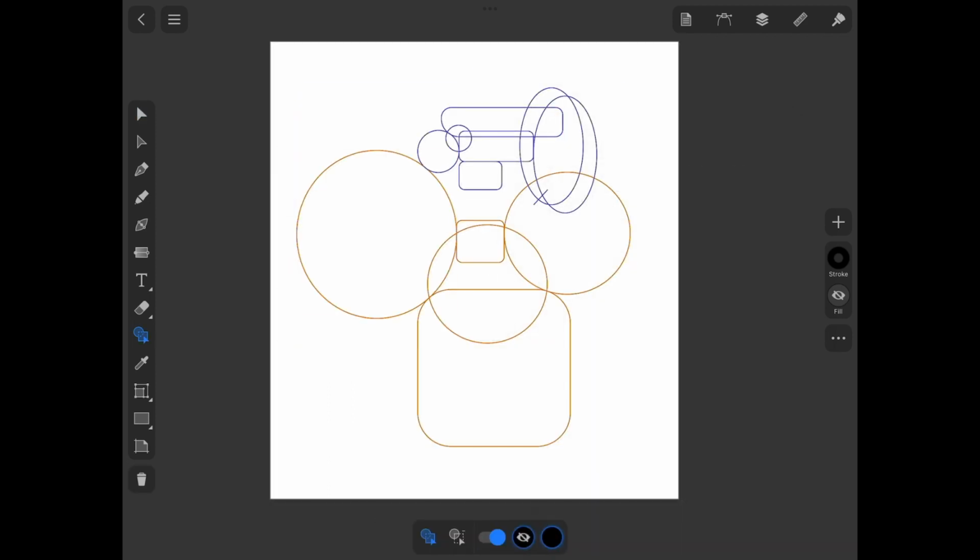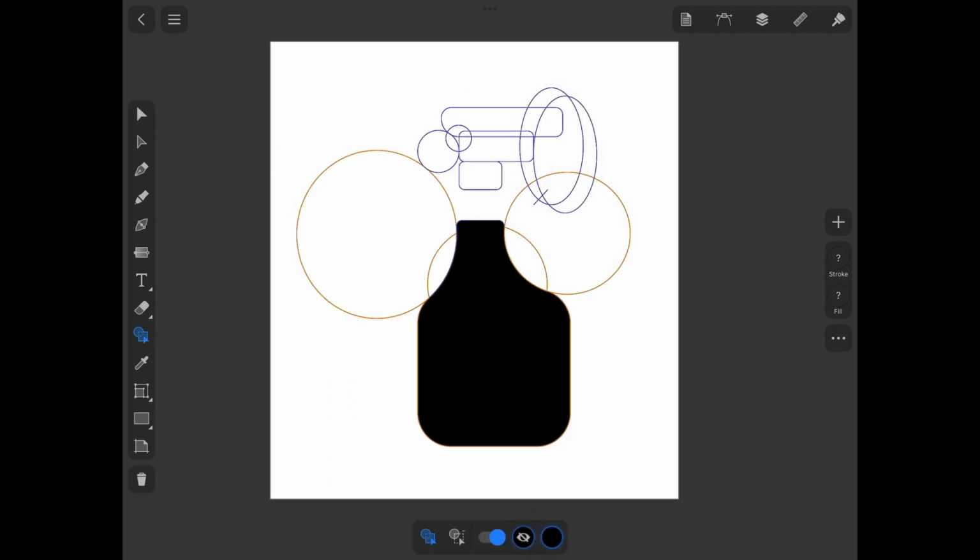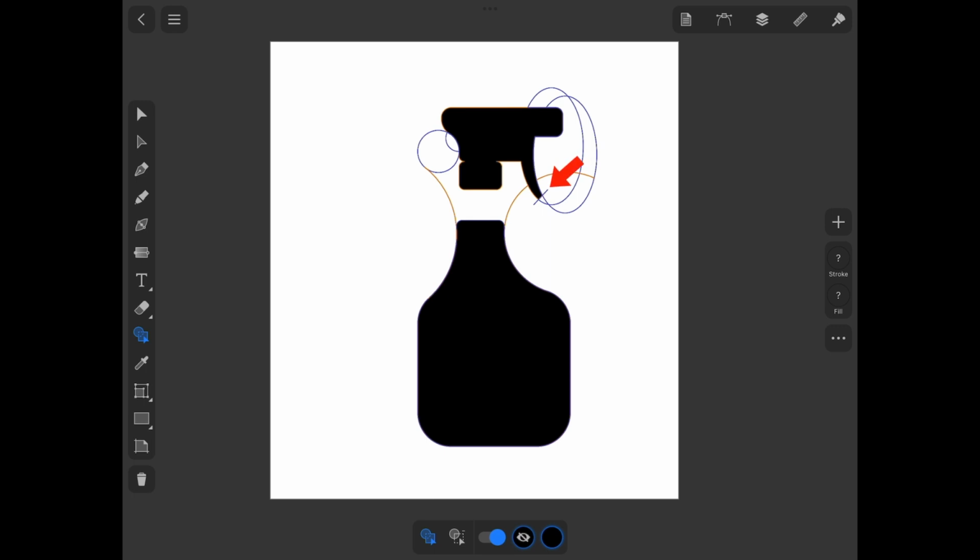Let's start merging parts that will create the icon. Then we're going to erase the unneeded elements. The second part of the icon is a bit more complicated. You can see that the Fusion tool allows us to use a straight line or unclosed path. But such a path must form a closed area together with other paths or shapes. This line is used to terminate a spiky element that is created with 2 ovals.